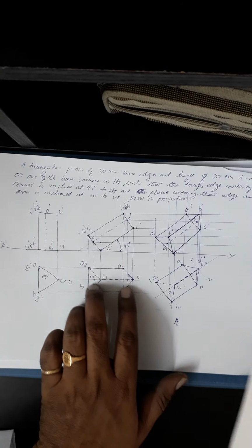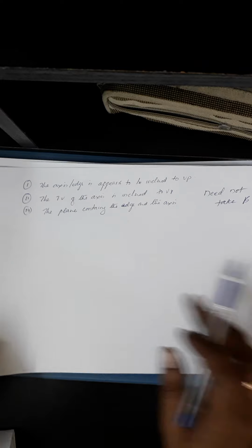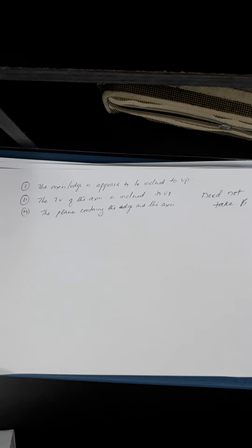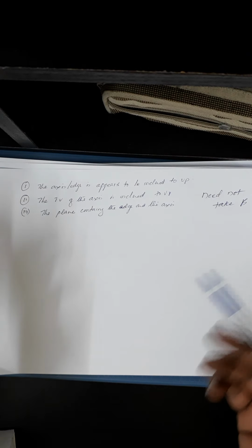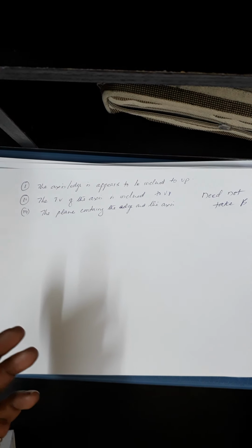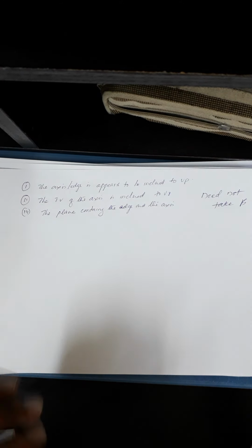So whenever you have apparent length, if the given inclination is the true inclination, then you have to go for finding beta. Whereas if you find these three sentences, the given angle is directly beta. In that way you need not take beta again. So directly you can draw with the given inclination. If you find these words along with the inclination.